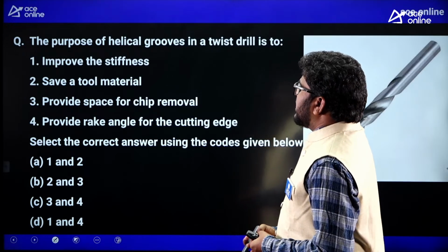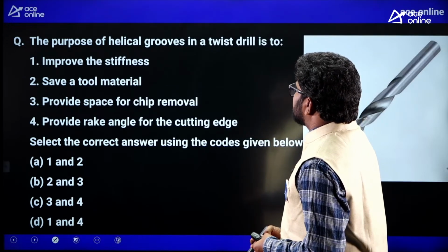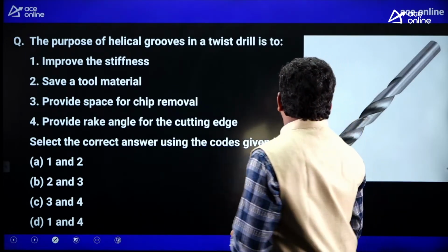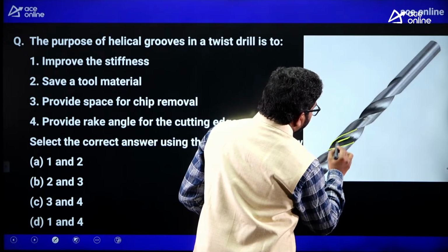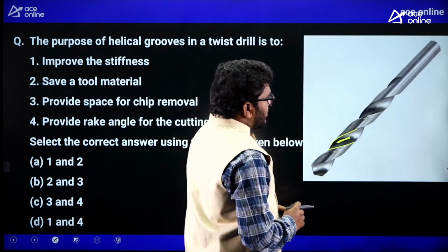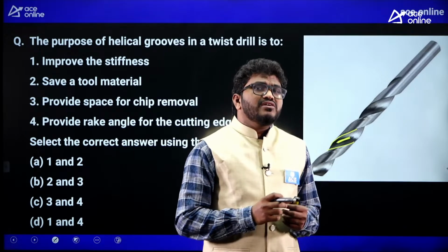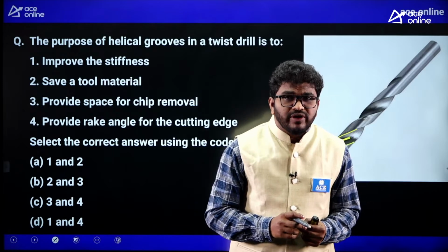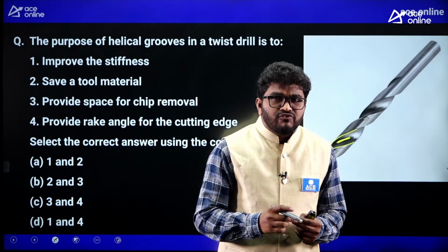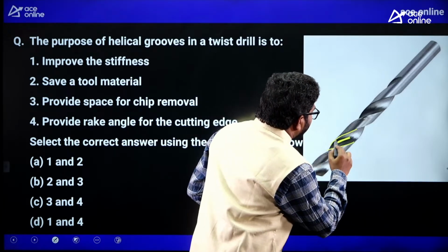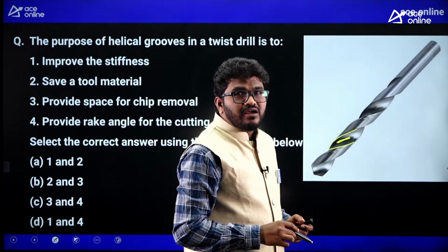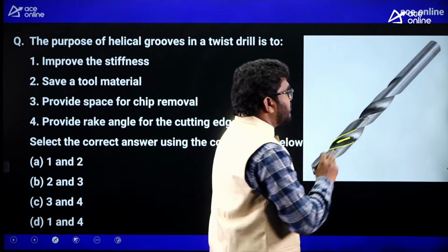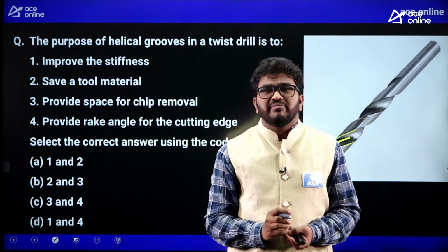The purpose of helical grooves in a twist drill is to... the purpose of helical grooves. This is a helical groove, okay? Why are you providing this helical groove, tell me? It acts as a passage for workpiece material after cutting. Okay, it acts as a passage of workpiece material after cutting. That is the main reason.